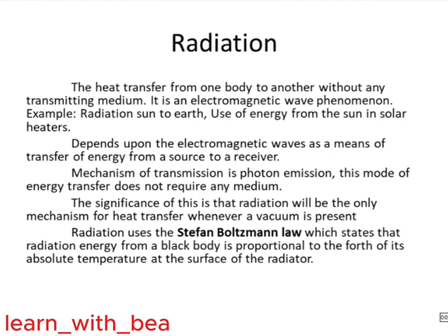The mechanism of transmission is photon emission. This mode of heat transfer does not require any medium. The significance of this is that radiation will be the only mechanism for heat transfer whenever a vacuum is present. So if there's a solid, we use conduction. If there is a fluid present, we use convection. And if it's a vacuum, with no transmitting medium, we use radiation.